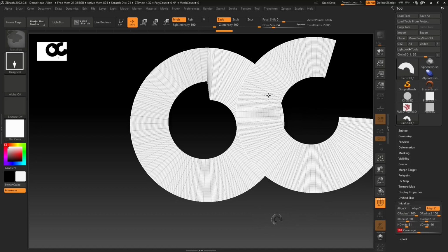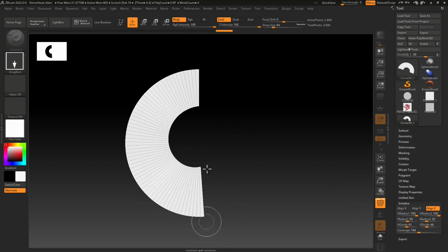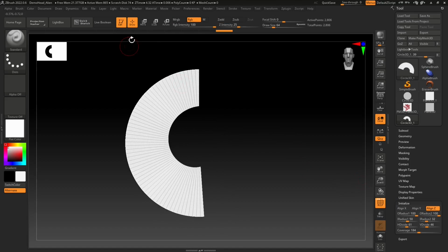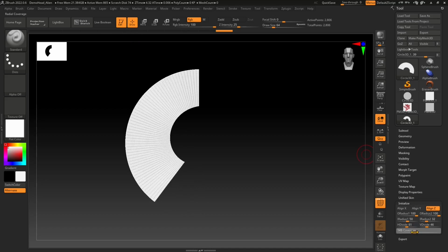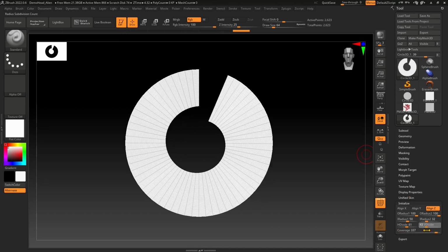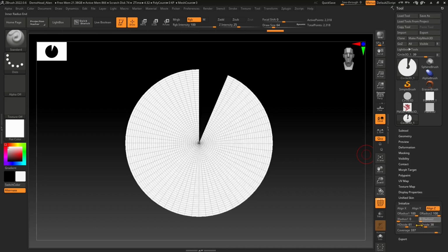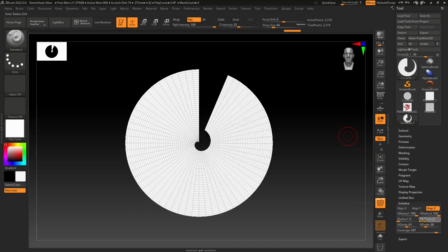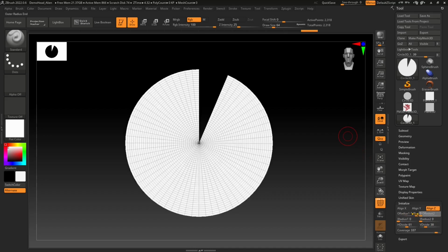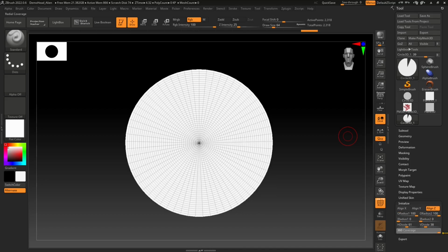So this is a little bit annoying because we need to create the shape before we can actually see the changes. Now there is a workaround for that. If I create the shape and move into edit, now I can see the changes in real time. So I can change the coverage, for example, or the various radii. You can see you have 4 different radii here, 2 for the external and 2 for the internal. If you change those, you can see how many different shapes you can get just by playing around with the parameters. And these are the subdivisions.